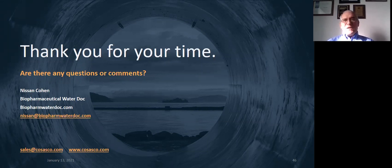That's quite a possibility. The point is that derouging and passivation should be based upon science and not based upon color or QC queasiness. So you can determine whatever that level is. Traditionally, when I've done these presentations before, we talk about 400 nanometers being probably a very good level. It's way below 1 micron.